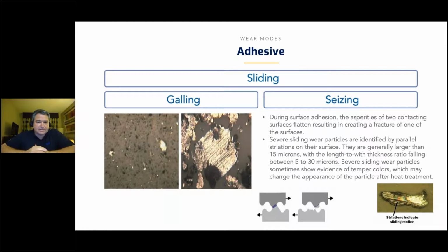In some cases, there's hydrodynamic lubrication, there's boundary lubrication. We're not going to go too far into that, other than to know that oil is there to bridge the gap. Film strength keeps things separated. Water does not share that quality. Water in your oil, water's not compressible. It has no film strength to be able to keep those parts separated.